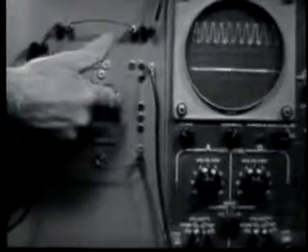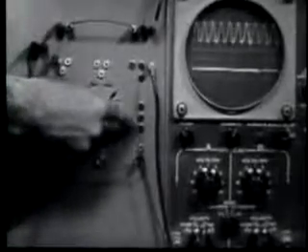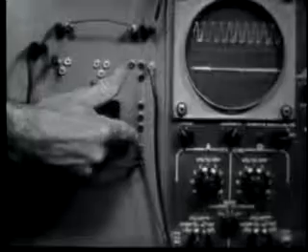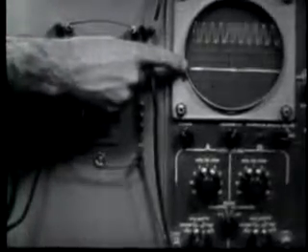Now, down here, in this circuit, is where we'll hook up our filter components. This is the series position, and here is the shunt position. Notice, as is always the case, the output is taken across the shunt component and is displayed on the B trace or the lower trace of the oscilloscope. Note also that, as we did in the first lesson, everything is grounded together. All right, let's plug in the components now.